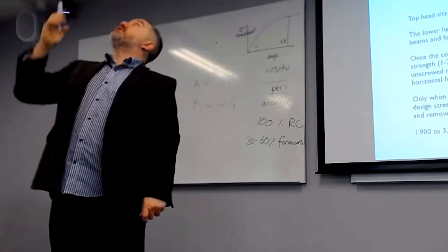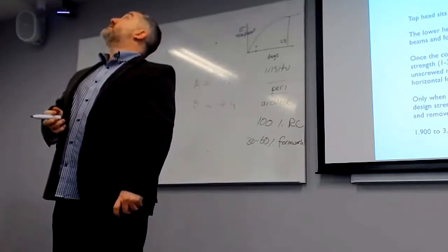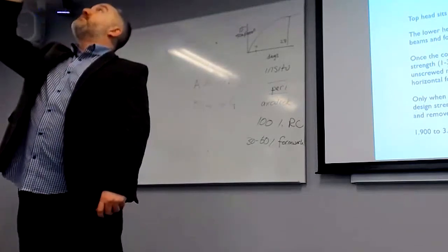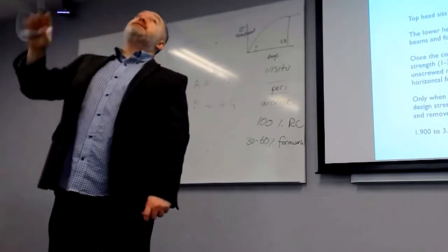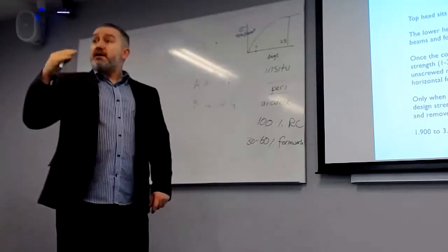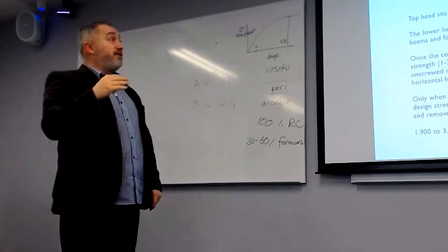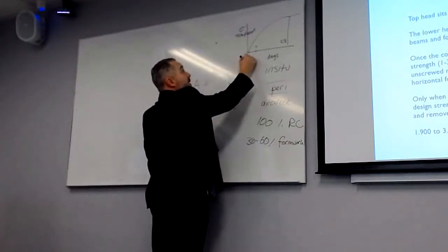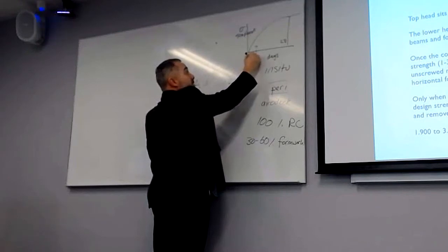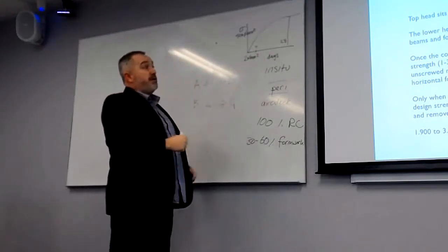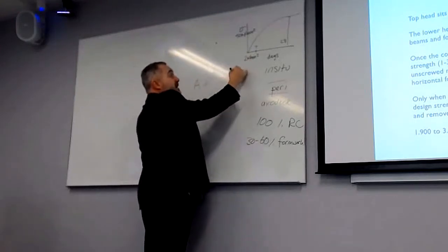That surface is okay. Looking at that precast, it looks like there are a few little air holes. That might just be the paint effect, but if you've got a final concrete finish, you've got to make sure your formwork is not going to damage it. And they say that once it's round about 2 newtons per millimetre squared, you can peel away the formwork. That's called striking.